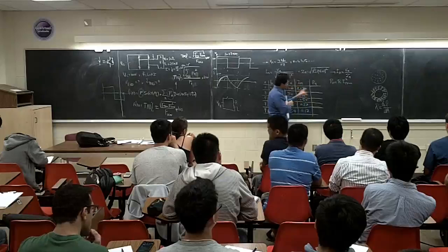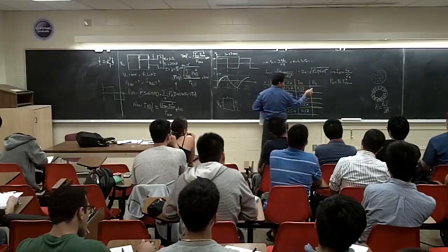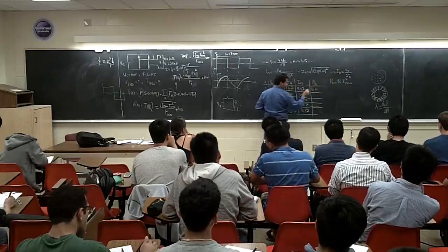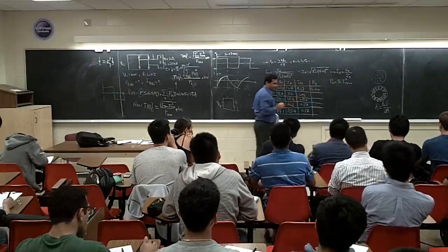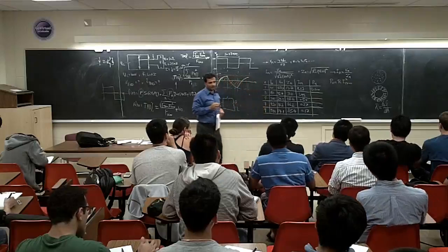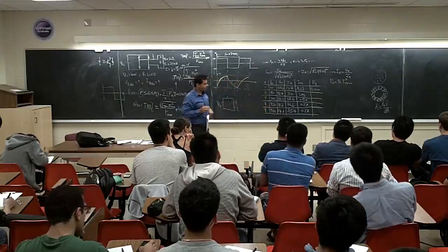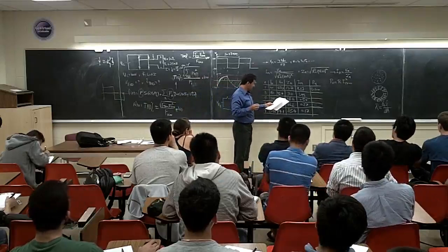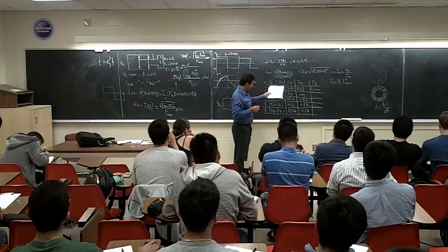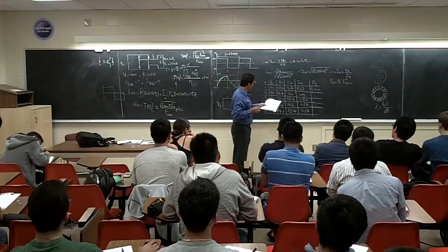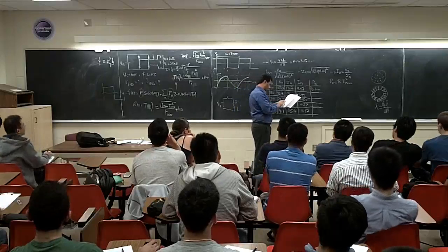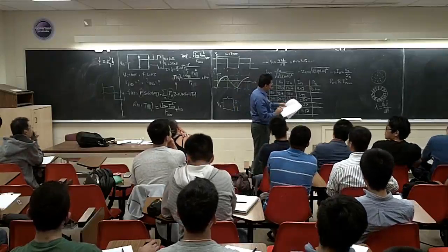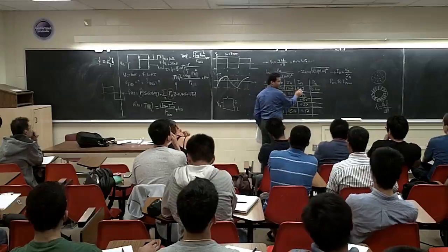So if I'm going to calculate this one, I'm going to put the detail here. P1 is going to be R, which is 10 ohm, times I1 RMS squared. Is the value I put here the RMS value, or the maximum value? Let me quickly verify that. These are the max values I have here.